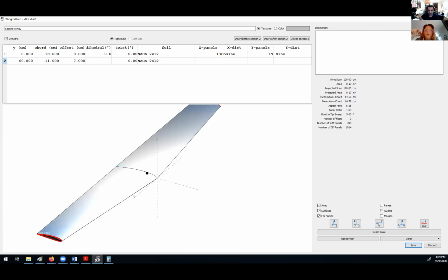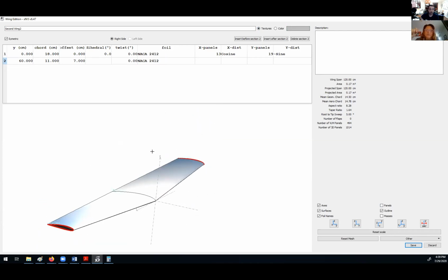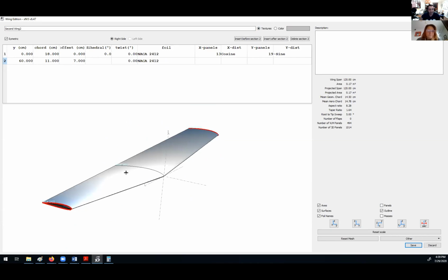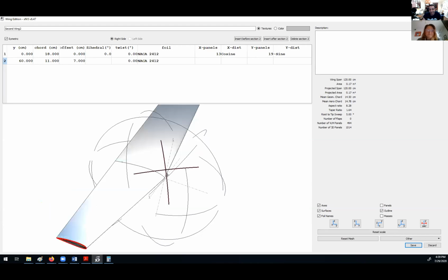Now, if I do a biplane, should the airfoils match? It depends on the design, for example, how much lift you want, what is the total weight. But this biplane configuration is no longer efficient for recent designs. These are for old World War II airplanes. They were thinking that adding the second wing helps to get extra payload. But they found that eventually it's more efficient to increase the wingspan than adding two wings at top of each other. This is the main reason that we no longer see those types of airplanes. But here I just want to show you that it's possible.